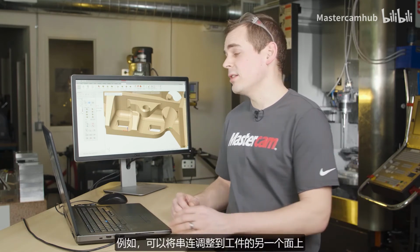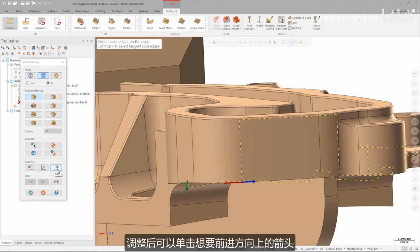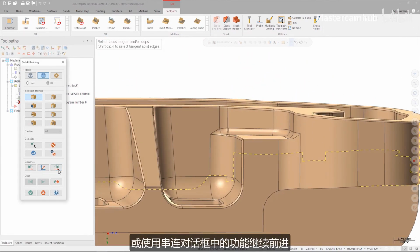The edges chaining method allows me the freedom to be creative in how I create my chains. For instance, I can adjust the chain to go back to the other side of the part. Once adjusted, I can continue to advance around the part either by clicking the arrow I want to follow or by using the functions in the chaining dialog.